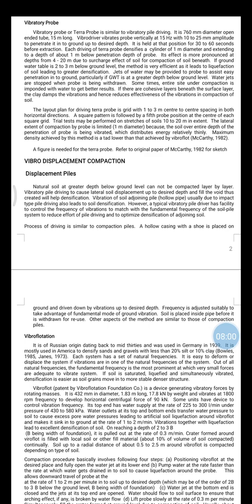So that's why vibratory pile driving is used to cause a lateral soil displacement up to a desired depth and fill the voids, thus helping densification. What the displacement pile does is displace the soil, so that due to the vibration, densification of soil takes place.